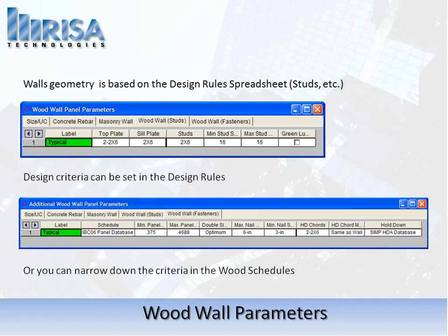So you can actually use green lumber design parameters or design calcs for that. The next one here is the design criteria for the design rules. First we were talking about geometry, and now we're going to be talking about the actual shear panel design. The first thing we lay out is a schedule for that shear panel design, and we'll see that in just a second. In that schedule, on the outside of those design rules, we can say we'd like to size these shear panels to be at 5/16 starting out, or this one here we've got 3/8.